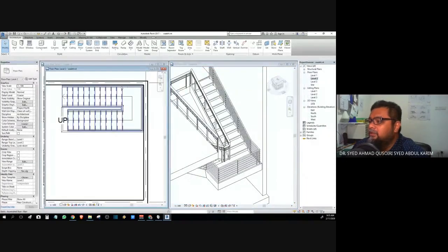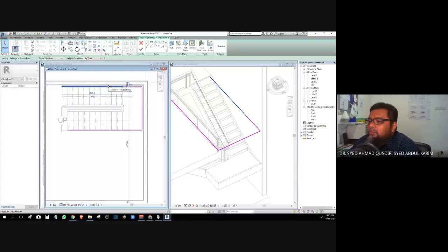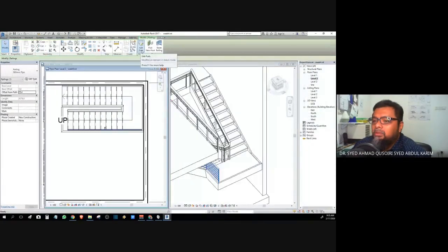So we highlight the rail and then we can click here, edit path. So same process, we can delete. So we do not want any railings here. Click yes. And we want this to be bottom glass panel also.